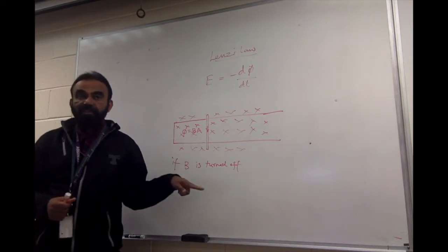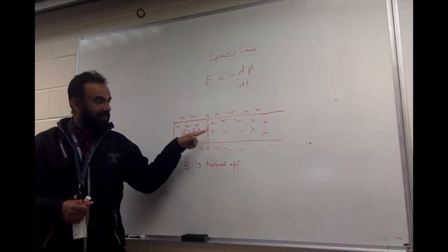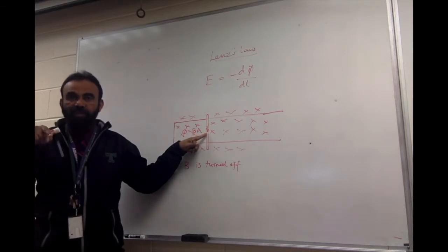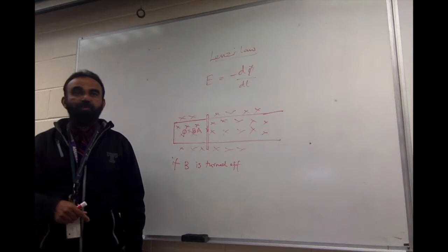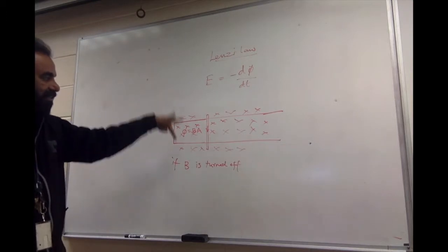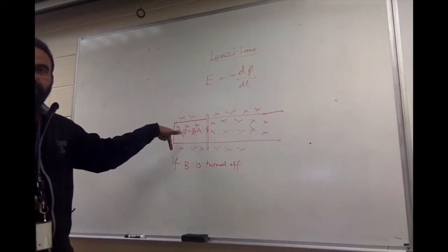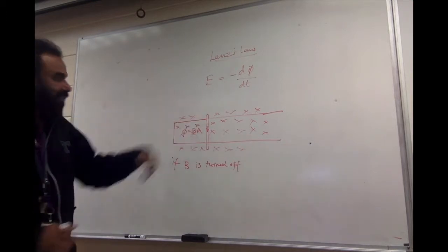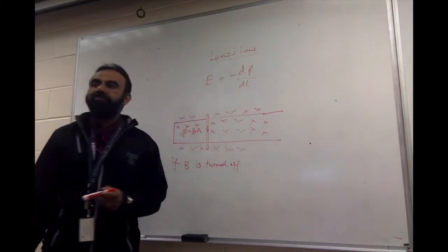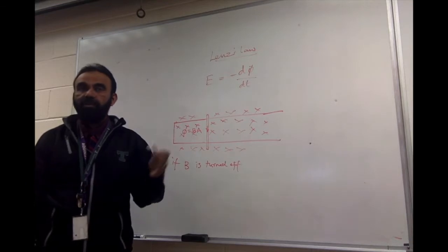Now, when the induced current flows in that manner, look at this conductor. There is a current flowing in the conductor, and it's placed in a magnetic field. So which way will it experience a force? Use your left-hand rule, Fleming's left-hand rule. Current is down, magnetic field is in. Which way will it experience a force? So what will happen to this rod? It will roll off.